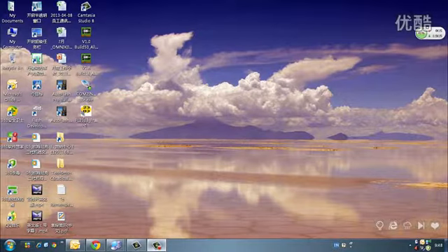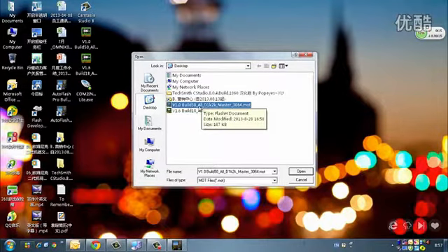After finishing installing the driver, click on Auto Flash Pro. The COM port will automatically show itself, and you just choose the file you want to update to your inverter. As we're using the 1.5, we're going to choose this one.